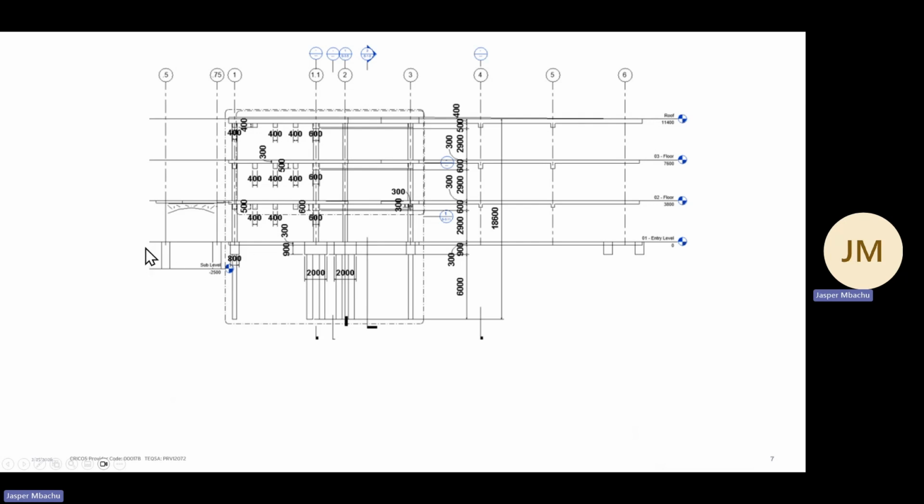So that seems to be within the ground, and anything in the ground supporting any structure should be a pile, not a column. And if it is a pile, then we should be including it in our substructure measurement. But let's assume that that is not the case, and we don't want to go into that. I think we'll revisit that in the second assignment.